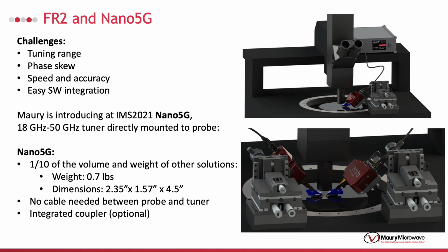It's also important to mention the tuner is based on a 1.85 mm structure, allowing the second harmonic of 28 GHz to pass for proper measurements and eventually active tuning. In the next slides, we'll be talking more about tuning range and phase skew.